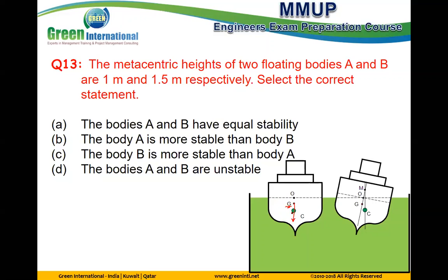But on the other side is the buoyancy force, the other force that keeps this body in stability, in equilibrium. This force, buoyancy, is acting on a point called C, the center of buoyancy, and going up. As you see, the two lines of action of the forces are on the same line. This body is stable.